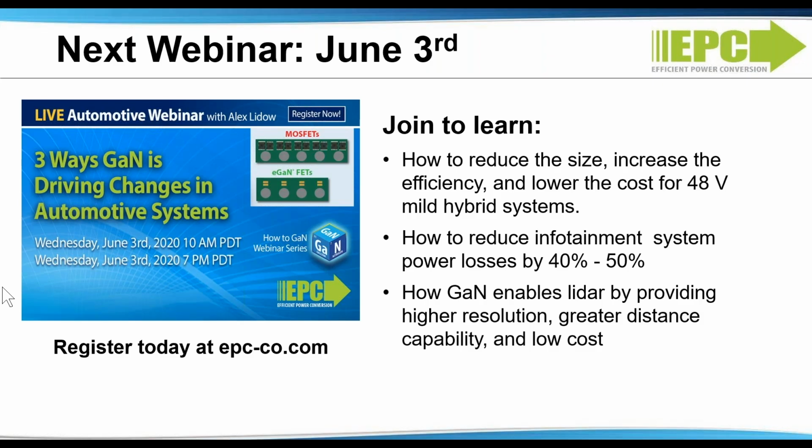The PCB traces under your parts carry very high currents. Do you see any issue with this? There are always going to be issues if you don't think about it. They carry high current. You can use vias to both increase the amount of copper that's conducting the current and also improve the thermal conduction away from the device.